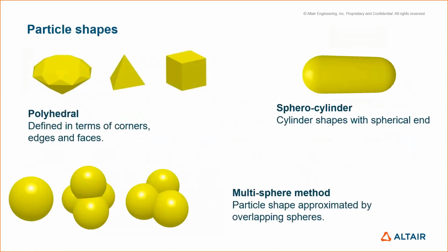Moving on, I'd just like to present a few different ways of modeling shape in EDEM. Spheres are the simplest shape to model. However, we don't get any interlocking. A perfect sphere really will rotate very easily. We use spheres typically for pharmaceutical powders, where the shape of the powder maybe is irrelevant, and the cohesive and the semi-static nature of the material really prevents rotation.